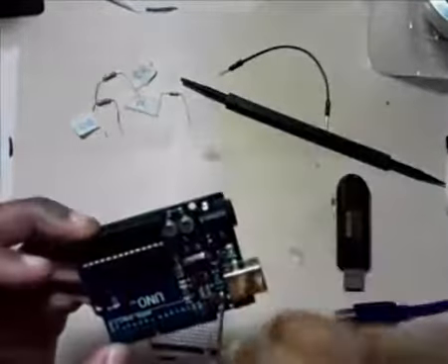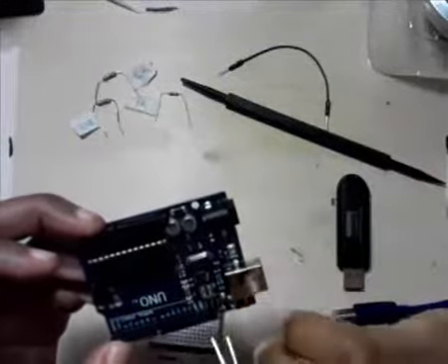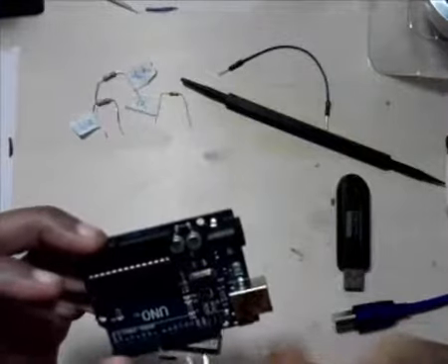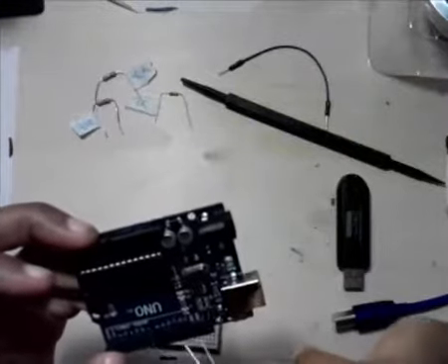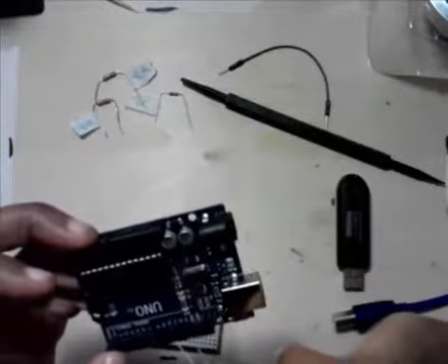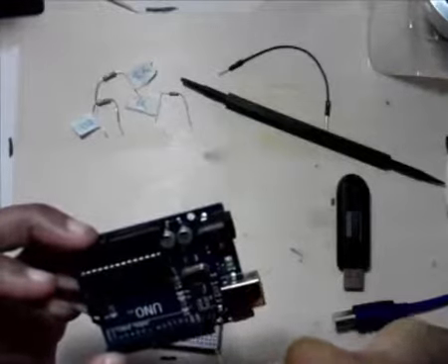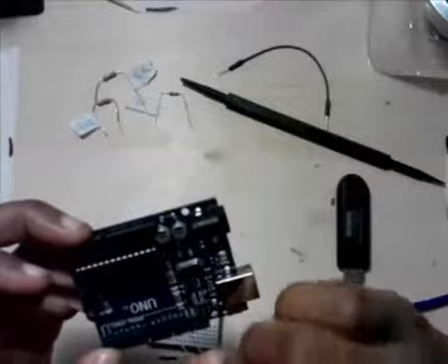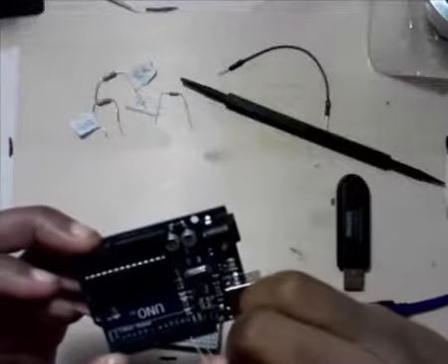Your longest lead is going to lead to a skinnier part in the LED. That's your voltage, or your positive, I guess. So your ground is going to go in the ground in this Arduino. We want to put the negative in ground. We want to put the positive in 13. So that's what we're going to do here.